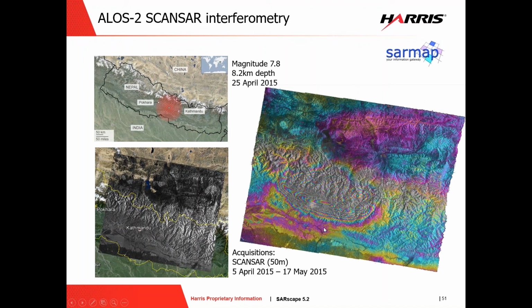So we see that also in this case it is unfortunately very nice to have access to large area data. With one acquisition, we can consistently cover the full pattern of the deformation for several hundreds of kilometers, covering all the region of the valley around Kathmandu. And you see also in this case we have 5 sub-swaths covering 1, 2, 3, 4, 5, covering the whole area. So they have been processed and merged together in a seamless way. So no phase discontinuities in this large area interferogram.